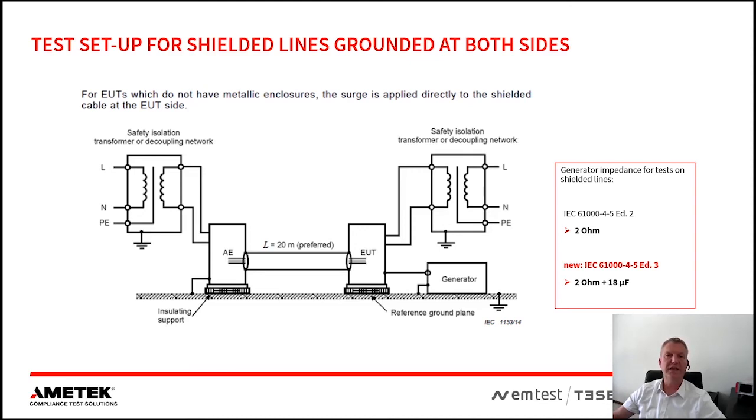For EUTs which do not have a metallic enclosure, the surge has to be applied directly to the shielded cable at the EUT side.